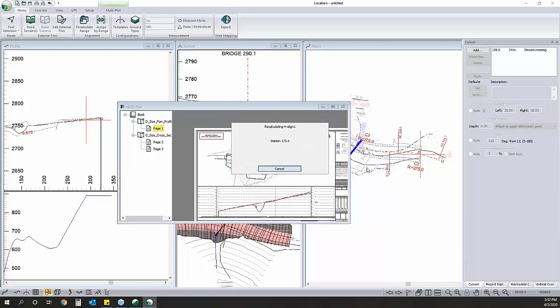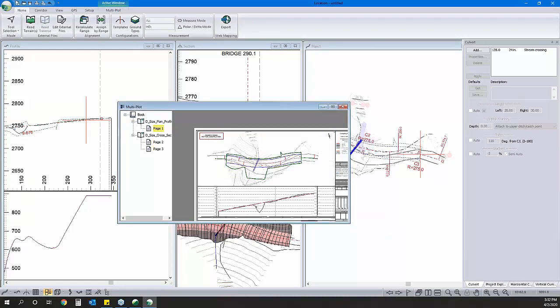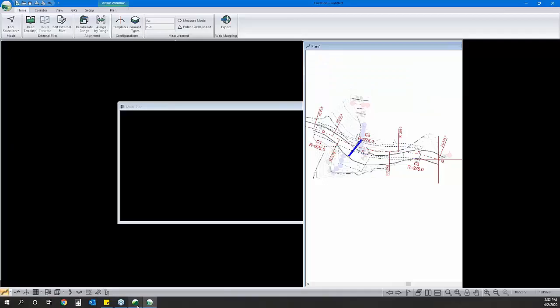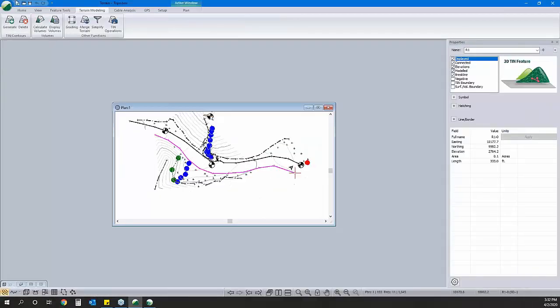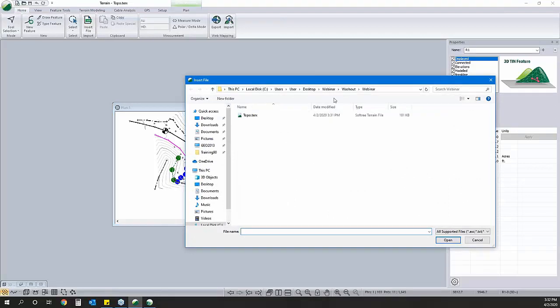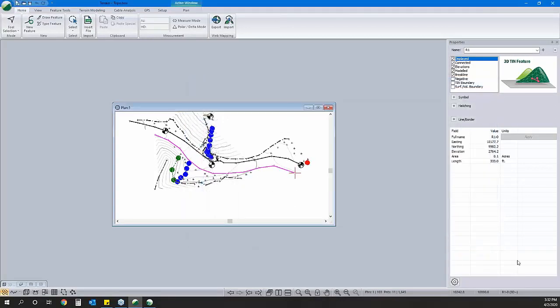Continue. And then we've got a little more wiggle room down here. So if you had additional survey data, the premise is the same, but instead of me just arbitrarily drawing lines, you can come in here, hit insert file, and reference in another ASCII file or whatever format you had for your additional data.